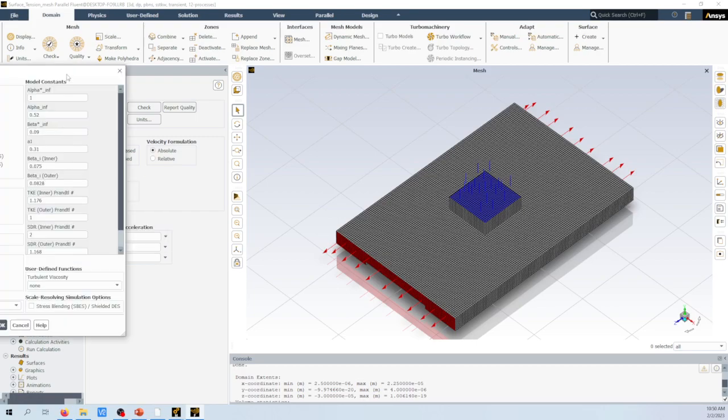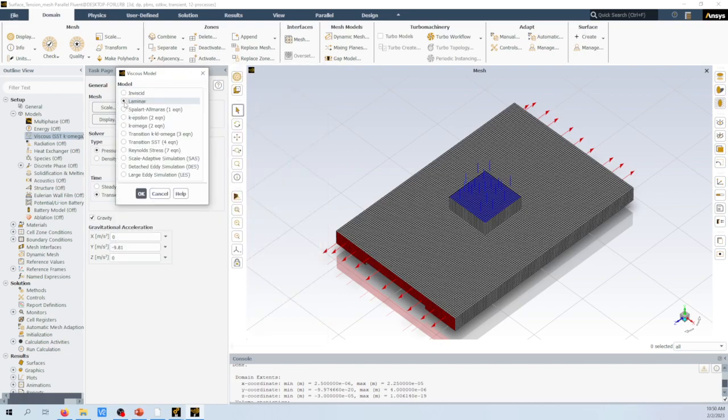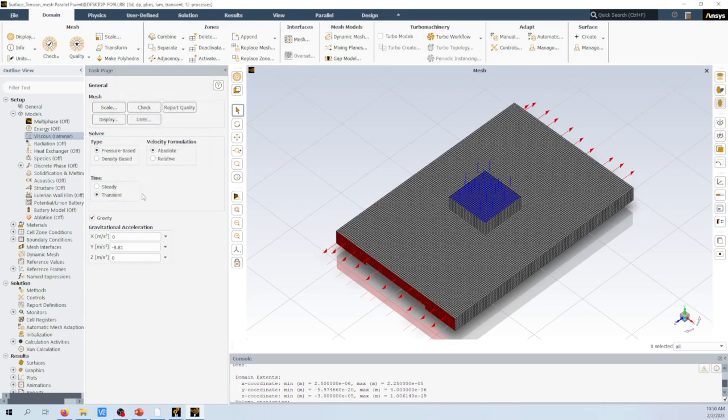Viscous. So if you do a Reynolds number analysis for this geometry and use 1 micrometer as the characteristic length, you will get a Reynolds number about on par with the flow speed. This flow speed will not be very high, it is assumed. It's driven by surface tension. It won't go over 10 meters per second. So with a Reynolds number less than 10, we can say it's laminar flow.